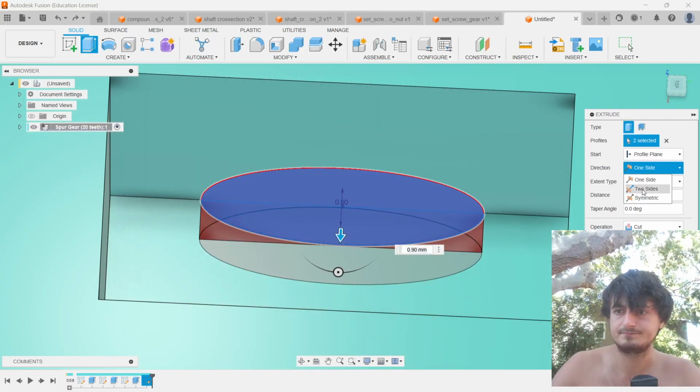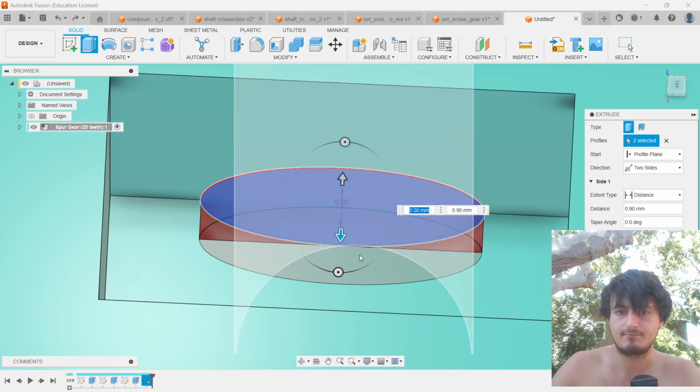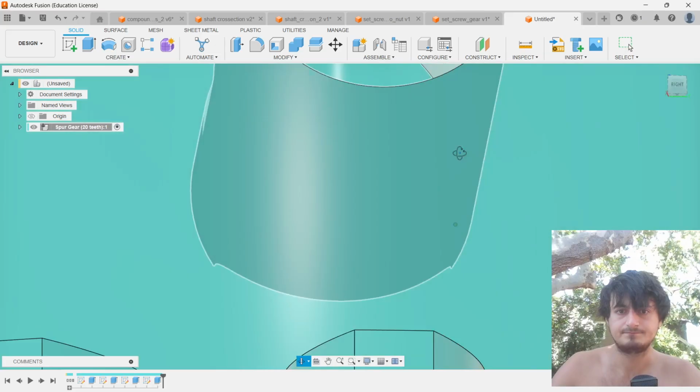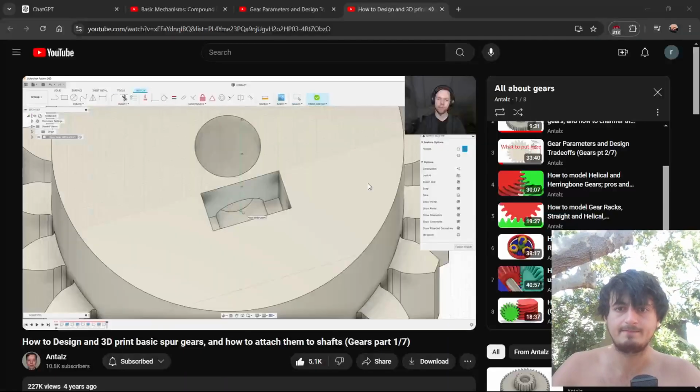And for that, I again click this surface over here, create a new sketch, and what I will do now is under Create, Polygon, take a circumscribed polygon, and then you want to look around here until you get this concentric constraint on the circle that we made before.